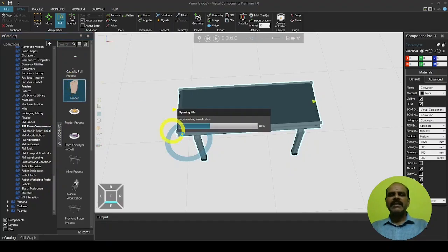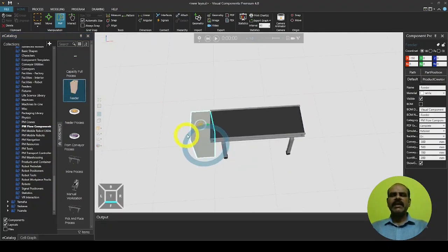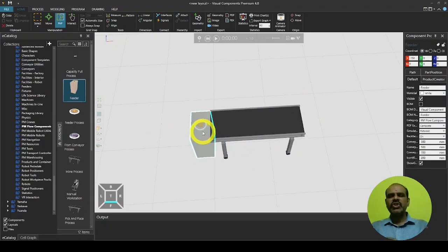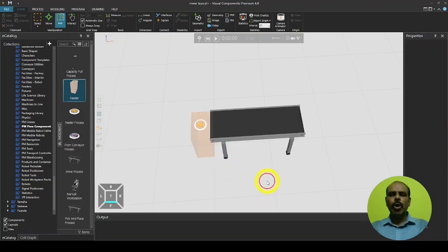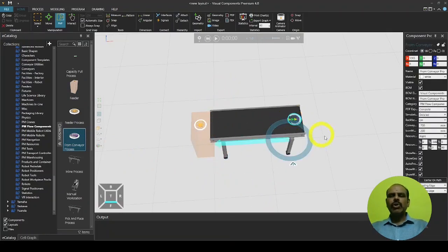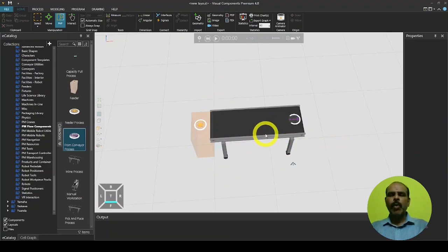In the previous exercise, as beginners, we searched everything. We went to the search tab and searched. But upon experience, we should be in a position to pick and place components from their locations. So now we brought the feeder and positioned it. Then we brought the from process conveyor and moved it to the source point of conveyor number 1.